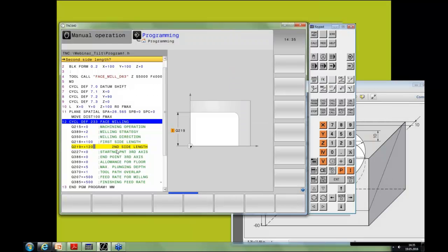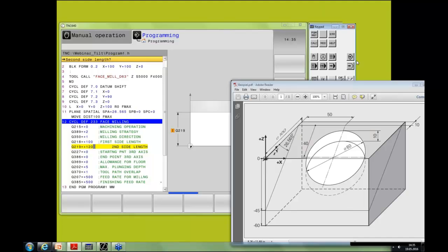So I program 120, and also the coordinate system on the workpiece looking like this. This value is X plus, and this value here up is Y plus, because we tilted A plus. So the coordinate system is looking in this way, and this here is the Z axis.